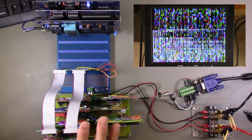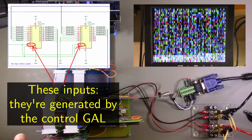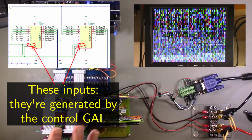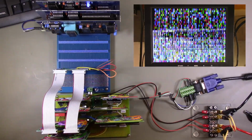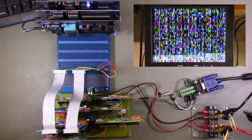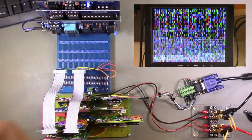So what I believe is happening is that the row begin address register on the readout module needs to get clock pulse signals that go high for one cycle to tell it when to load data into the 74ACT273 devices that store the row begin address. And I think what is happening is that there are glitches on that line that provides those clock pulses that causes the row begin address register to load data at the wrong times. And that's basically the reason for these artifacts that we're seeing.